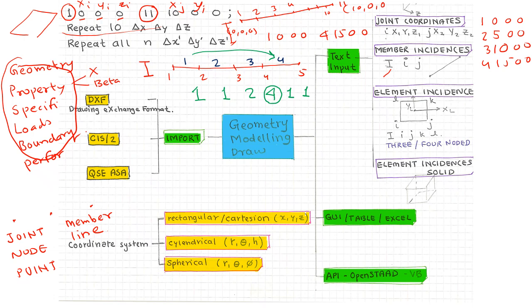If I want to create a triangle cell element, we write the element ID and then the 3 nodes. So here we have created a 4 noded element I, J, K, L. I, J, K, L. So you can move anti-clockwise or clockwise.